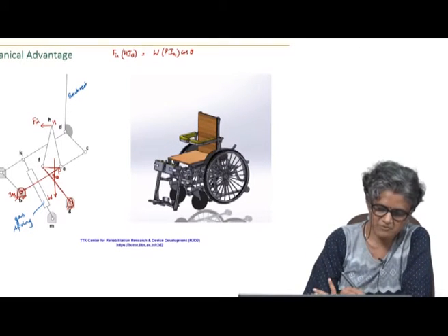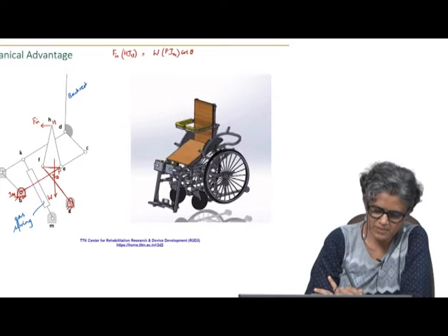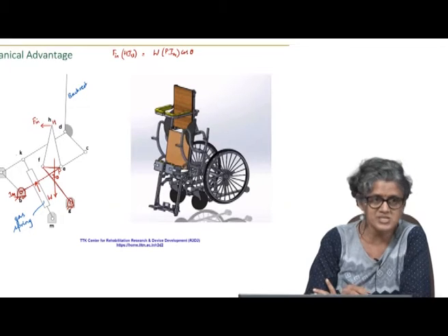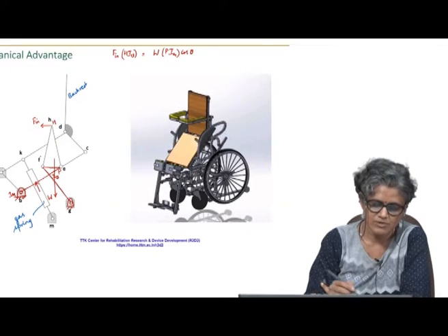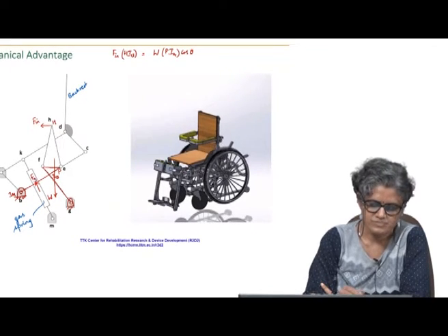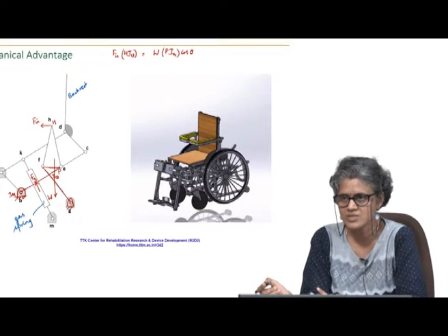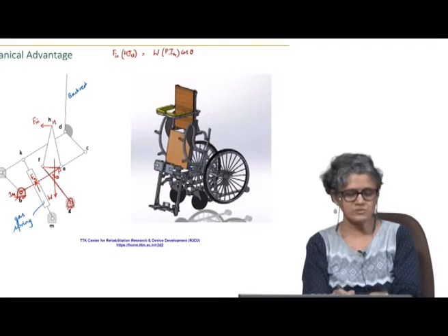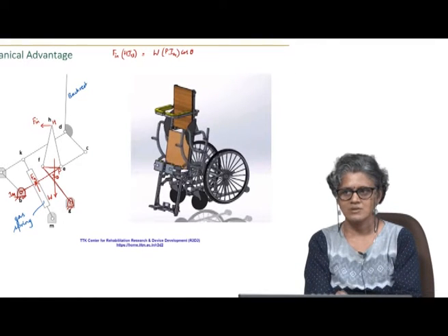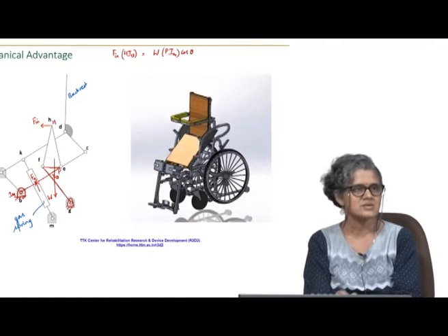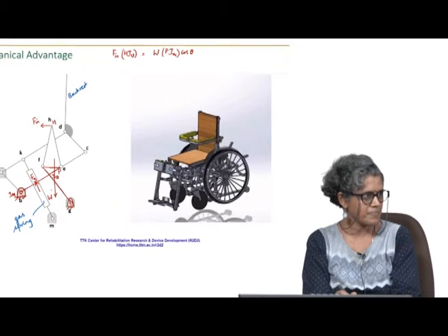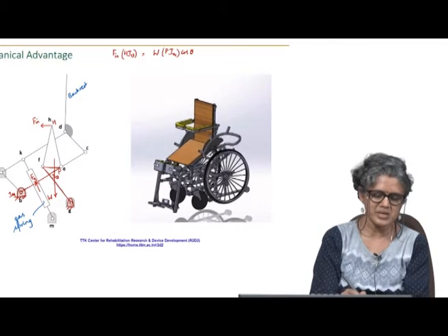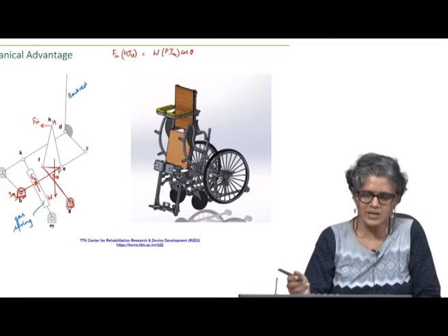And that is where we use this gas spring that now applies an additional force Fg on this linkage, which helps to balance the weight. Okay. So, I have Fg, I am taking this as perpendicular here, but that would act at some angle.